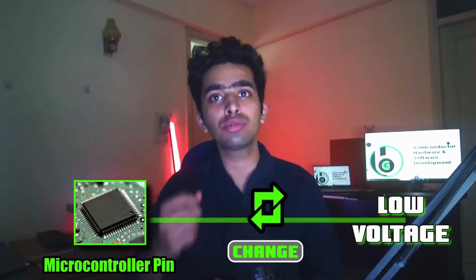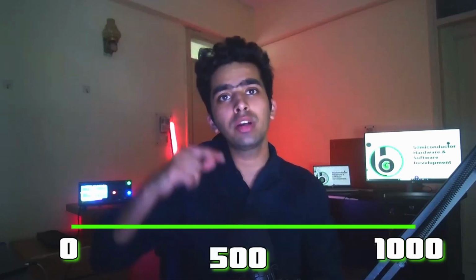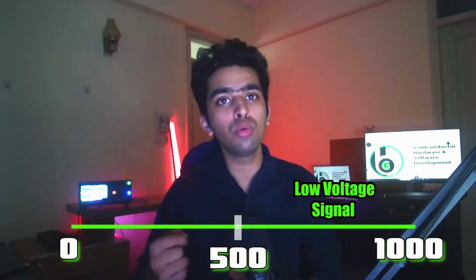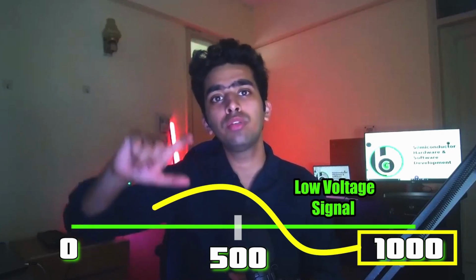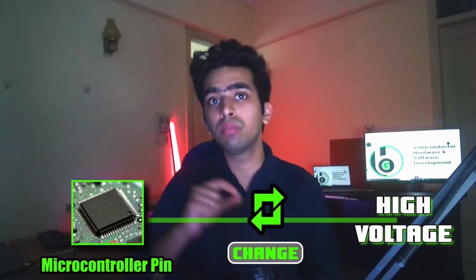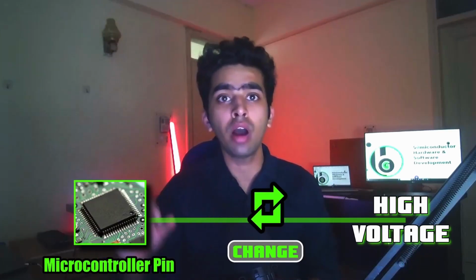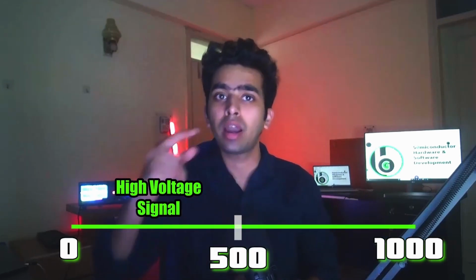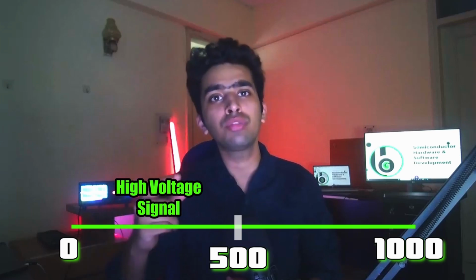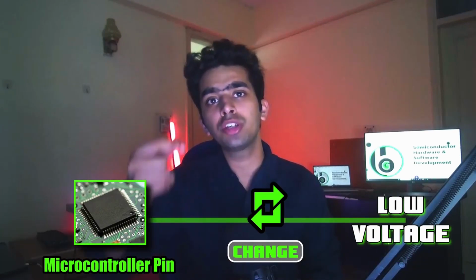Let's say it changes to the low value, and from 500 to 1000 it will then have a low voltage signal, and on reaching the 1000 value, the var counter value will reset to 0 and the microcontroller pin value is changed to high voltage. So now from 0 to 500, it will have a high voltage signal, and then on reaching 500, the microcontroller pin value is changed to low.